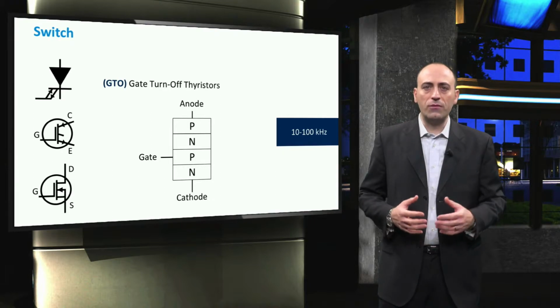A special type of thyristors used nowadays are the gate turn-off thyristors, which are fully controllable because they can be turned on and off at will. Thyristors are only used for inverters with a power of 100 kilowatts and above. There are other types of switches that generate an output with little harmonic content and that are fully controllable.